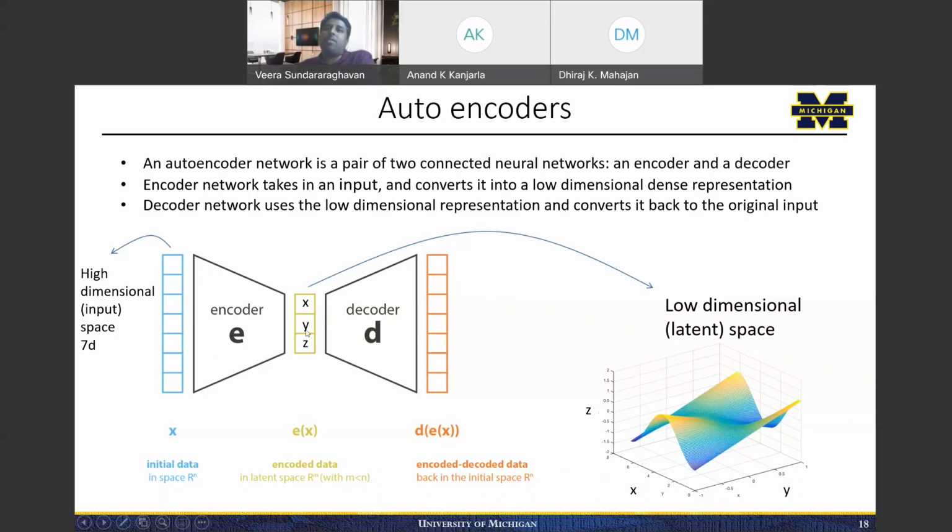So this is a low dimensional representation of the input microstructure. If your input microstructure is an image of a microstructure, which is 1000 by 1000 that you get from EBSD, then if you run it through this encoder, you can reduce that to a 3-dimensional space that you can visualize. If you have thousands of these EBSD images, you can reduce the entire set to a 3-dimensional space that you can visualize. That's called an autoencoder.